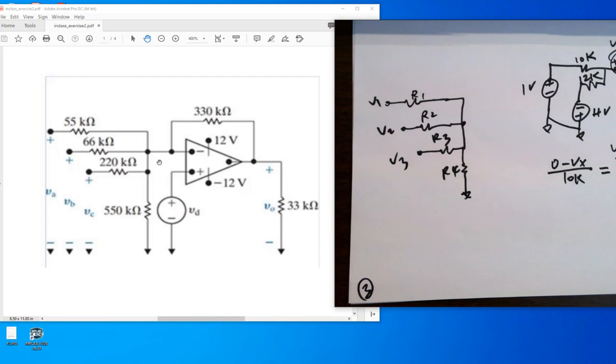We just use it because eventually it's a dual power supply and the signal will swing around 0. So we don't worry about lifting the signal DC voltage, like high pass filters, low pass filters, all these kind of things. It's making things easier, okay? So AC signal will just swing around 0 because that's the middle point of the op-amp. So we don't worry about the power supply, plus minus 12 volts.